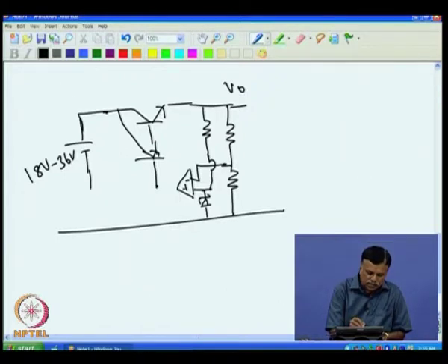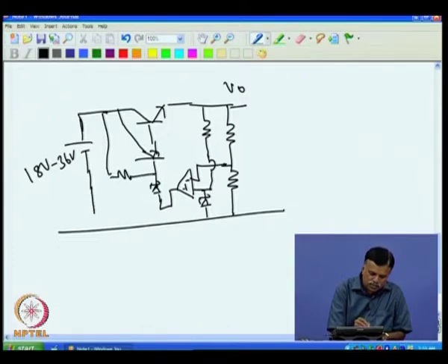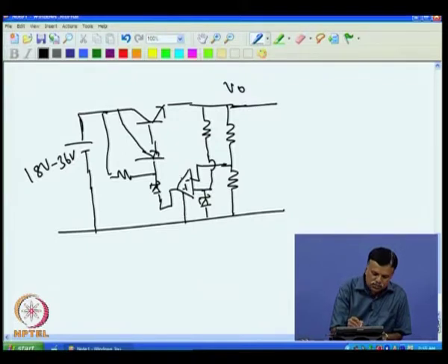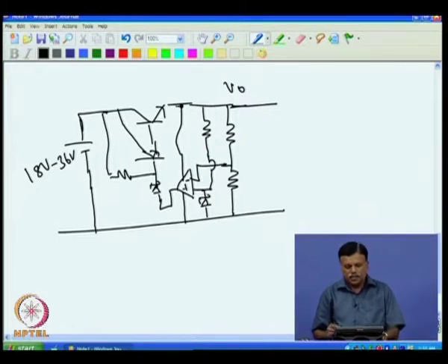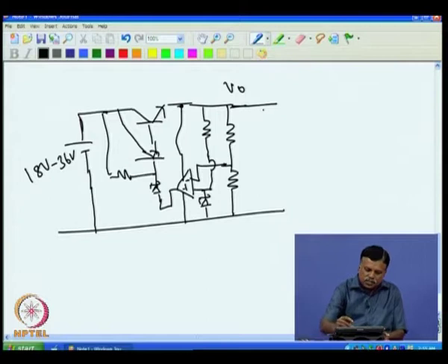There are various ways of obtaining this. I put on a Zener here, connect to this, then I connect a resistance here, and this I connect to this. Now, this is the voltage regulator that works, and for the supply I connect this to ground, and the supply plus input I connect to the output. This is the typical voltage regulator used in the 4 to 20 milliampere current transmitter. The output of this voltage regulator will be fed to a current transmitter. I will show you this.